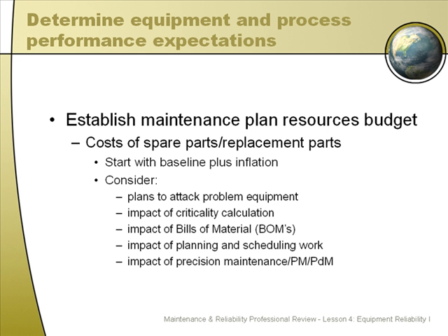Fourth, the impact of planning and scheduling work. Planned and scheduled work does not consume parts from storeroom inventory if it's done correctly. Planning allows you to order parts from vendors and outside sources. You shouldn't really be drawing down your storeroom inventory when you're planning. That's why you plan in the first place. So, the impact of planned and scheduled work should be to reduce storeroom inventory. The impact of precision maintenance, preventive maintenance, and predictive maintenance: preventive maintenance and predictive maintenance don't generally use a lot of parts, but if they do, they're usually low-cost, replaceable parts such as filters.